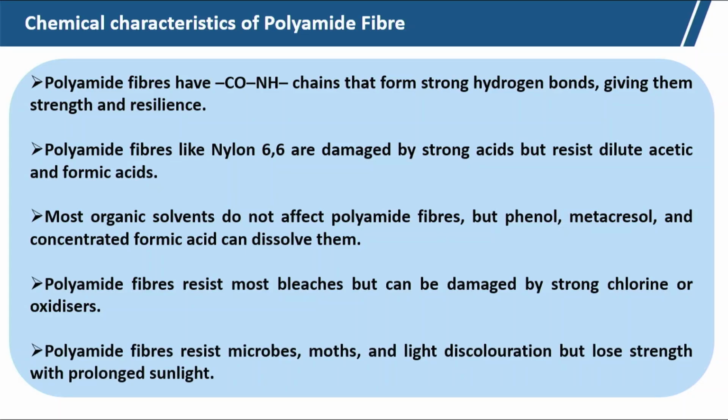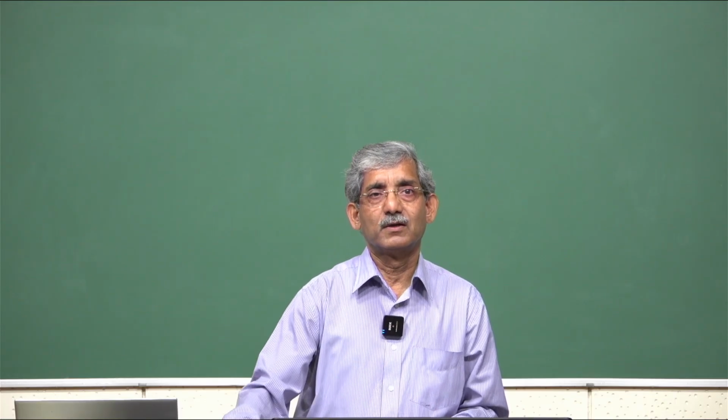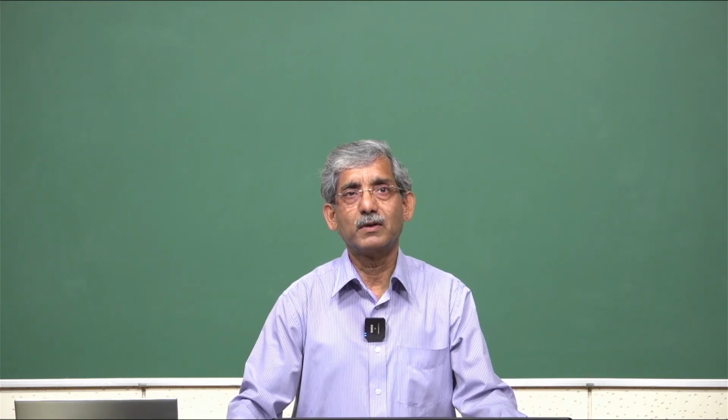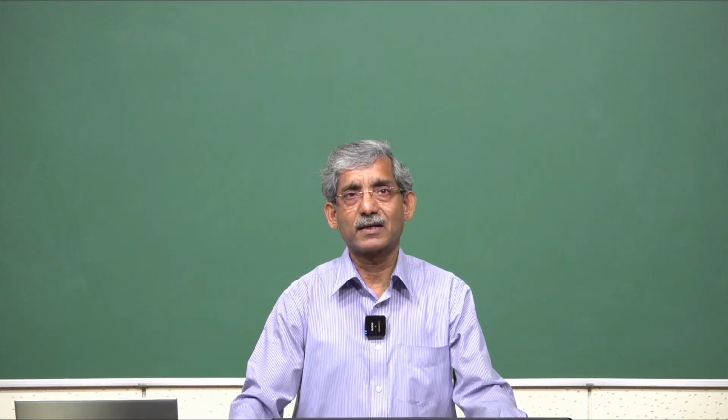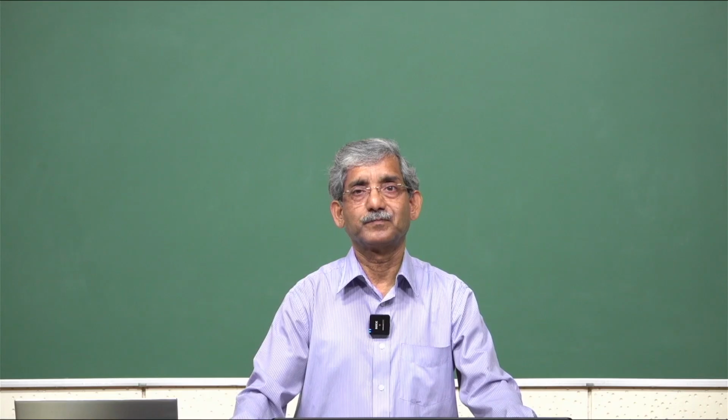Polyamide fibers resist microbes, moths and light discoloration, but lose strength with prolonged sunlight. So, we should not use polyamide fibers for outdoor application, because that will lose its strength. So, depending on the characteristics, we must select the application area.